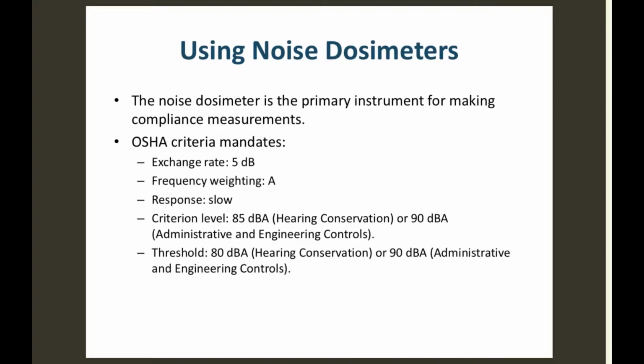At that point, you have to evaluate the worker's environment, decide whether you can control it below that, and among other things, you have to provide education, and you have to monitor the worker's hearing during the course of his career. Those standards start to kick in. The actual exposure limit for OSHA is 90. For NIOSH, it's 85. For OSHA, it's 90. So now that means you can be exposed for how long in a workday at 90 decibels?